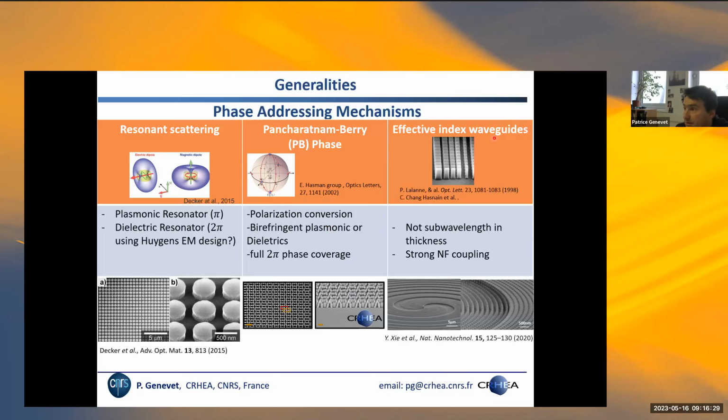And the third method, which is a bit more conventional, is essentially making nanopillar structures with varying diameters so as to operate as nano waveguides, if you want. And by changing the diameters of those nano waveguides, you change the actual mode index. And so you increase the refractive index of the waveguide by simply increasing the diameter. And you end up, therefore, for a fixed height, with a gradient of phase response at the output. So these are the 3 techniques which we were convinced we had and understood for the design of metasurfaces. We have here a review paper we wrote with Federico back in 2017.